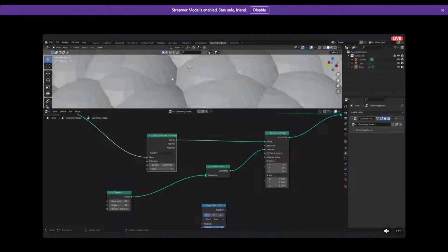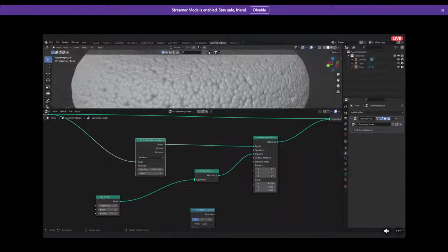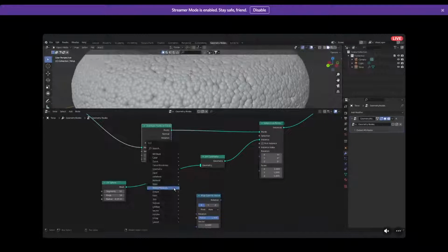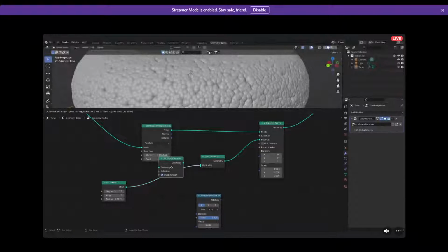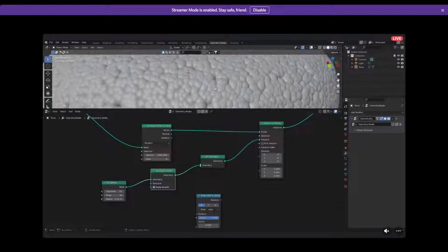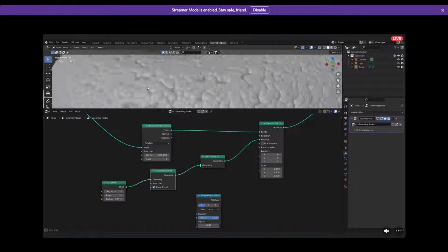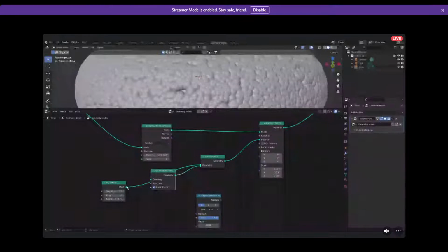And I don't like this faceted mesh. So what I'll do is similarly like the Shade Smooth, there's a node that does that. So Shift A and smooth. It's going to be Set Shade Smooth, and then you just hover it over the socket of your UV sphere and your Join Geometry, and that's just going to shade smooth like our command in the viewport or subdivision. So without, and with. Big difference.